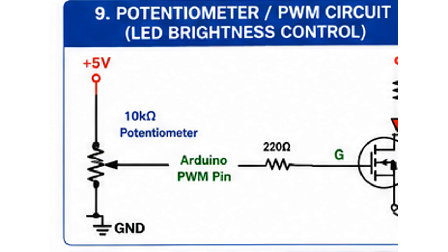BJTs remain excellent for many amplification circuits and certain switching tasks. The statement "MOSFET is always better" is not correct. The best device depends on voltage, current, speed, available drive, and cost for the particular application.